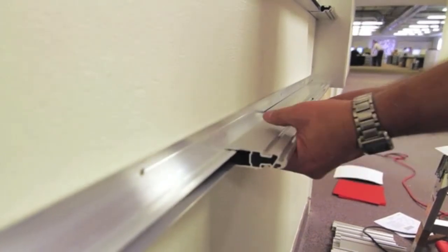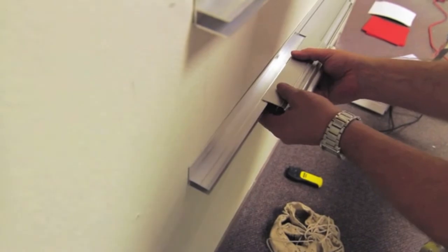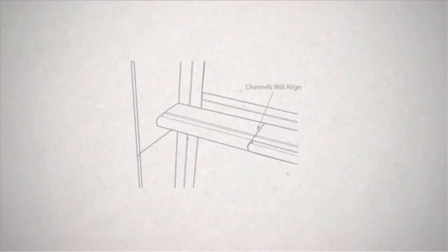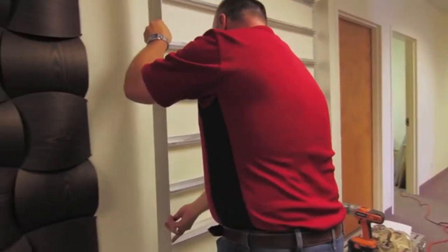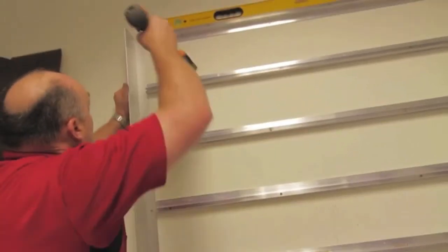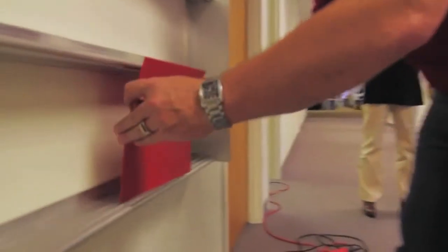To achieve your ripple, make sure you alternate the orientation of the outer extrusions when placing them both next to and underneath each other. You will notice that all the channels are aligned, but the grooves should not. Once all outer extrusions have been placed, fit the second end of edging extrusions against the ends of the erected wall frame. Now your wall is ready for the shadow tiles.